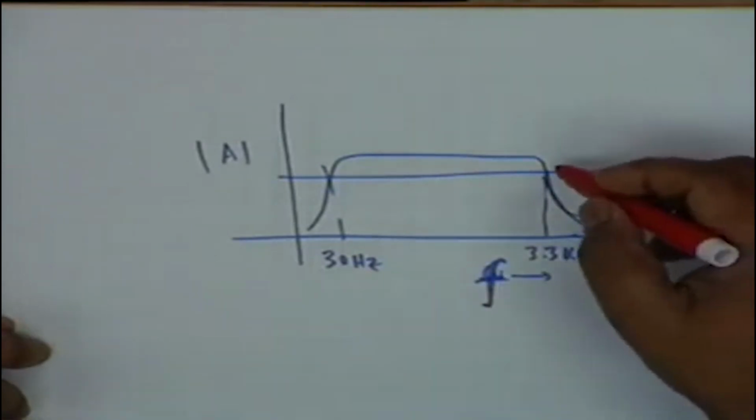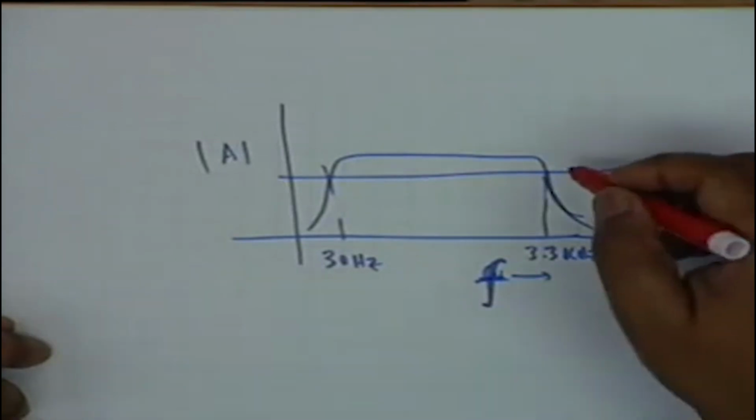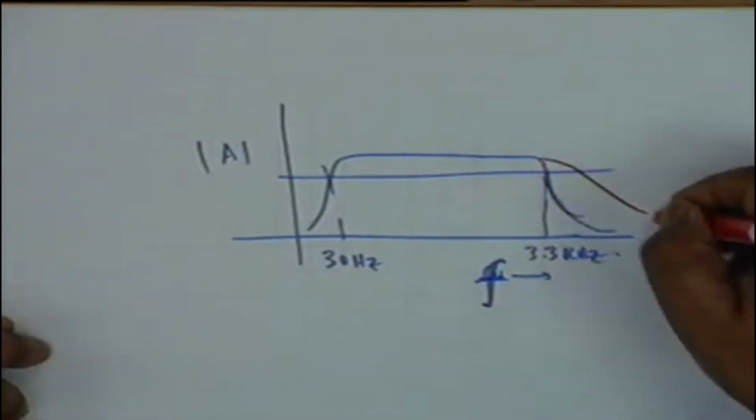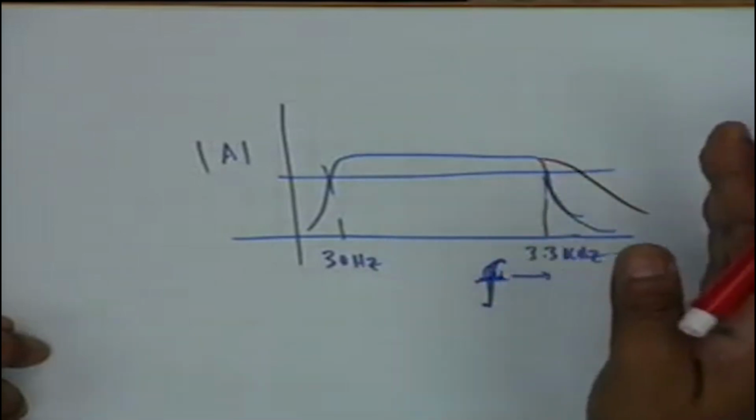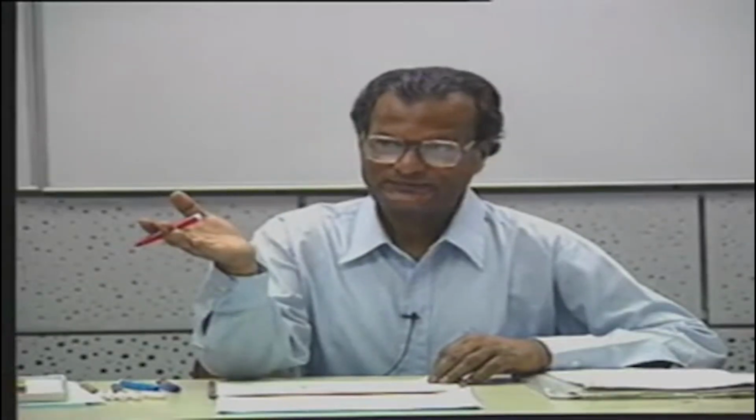On the other hand, if you increase the treble, this means that you are increasing the high frequency 3 dB point. That means you are admitting more high frequency, and therefore a violin will sound sweeter if the treble control is increased.